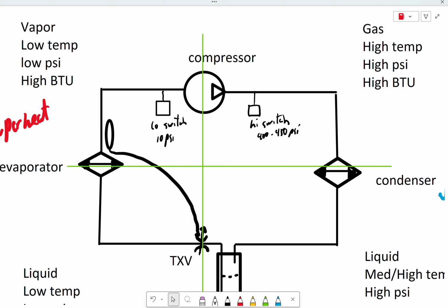If the expansion valve is wide open, because it's sensing a huge amount of superheat, because there's no refrigerant in the system, that means that the compressor is going to click on. There's not very much refrigerant in the system, so it's going to suck the low side empty, and it's going to kick off. But because the expansion valve is wide open, the pressure is going to equalize very quickly from the low to the high side. The compressor clicks back on. And you guys, a rapidly cycling compressor and a low charge, do those two things go hand in hand in your mind? It should, and that's the reason why.